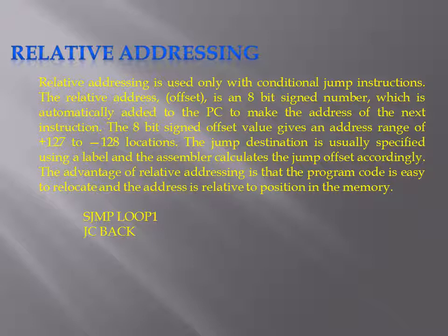Such jumps are like SJMP loop1 or JC back. In this way the jump can move forward or backward with the help of the offset.